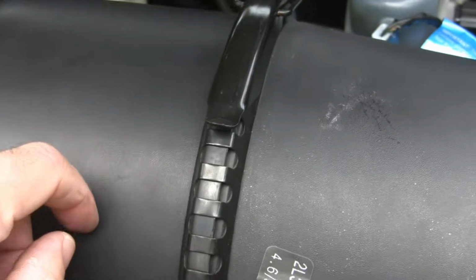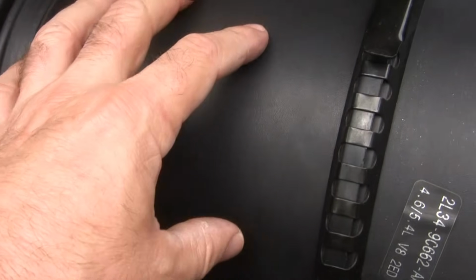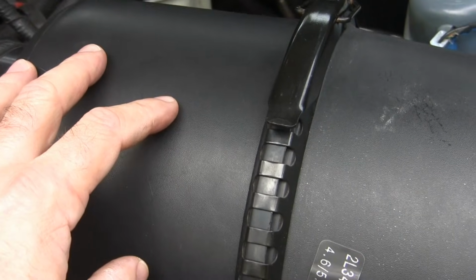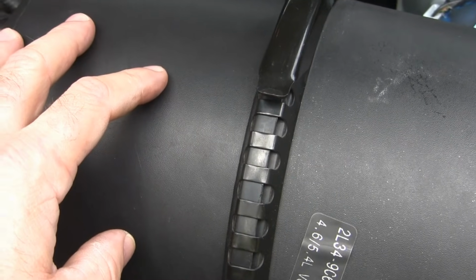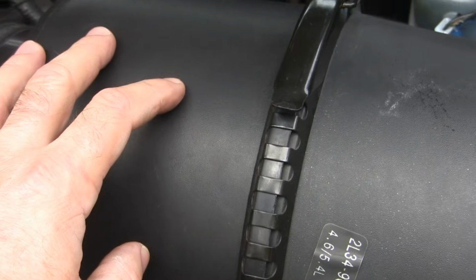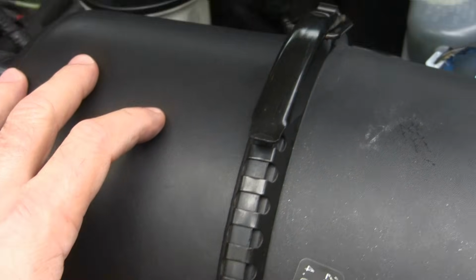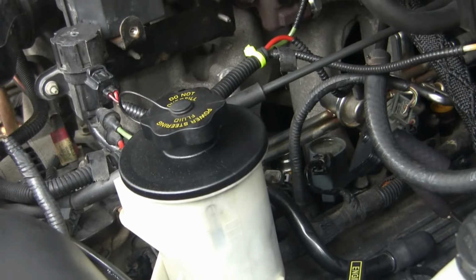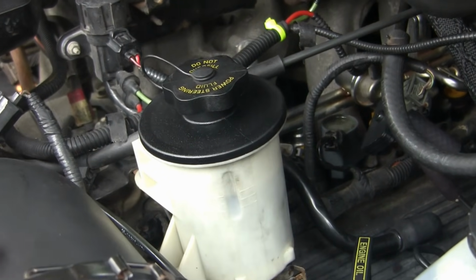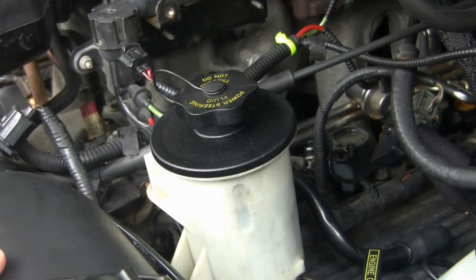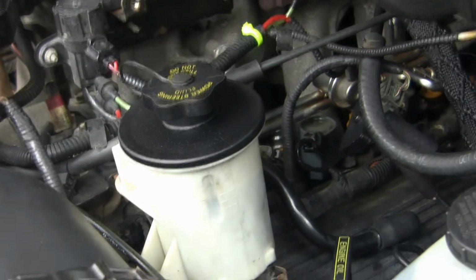And when you take this out, you'll see the little sensor in there. It's just like two small wires. Looks like very small resistors on them. And a lot of times what happens, they'll get dirt on them. And they're very sensitive. And there's a special product called mass airflow sensor cleaner. CRC makes some. It's pretty expensive, around $8 a can. But just take this guy out and spray that pretty heavily. Don't ever touch it with the end of the nozzle or your hand or a screwdriver or a Q-tip or anything like that, just the spray. Then let it dry and put it back on.